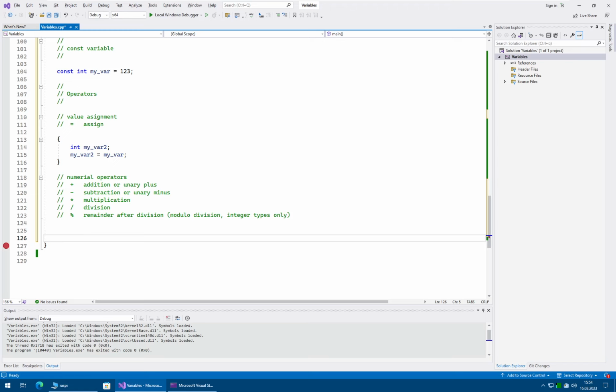So these vector extensions, which you can find in modern CPUs, are labeled as MMX, later SSE, then SSE2 and SSE4. Now they are labeled AVX, and this goes up to AVX 512-bit. So in fact, you can have a vector of quite many integers, or this also works with floating point numbers, and then do one operation on the whole vector of numbers.